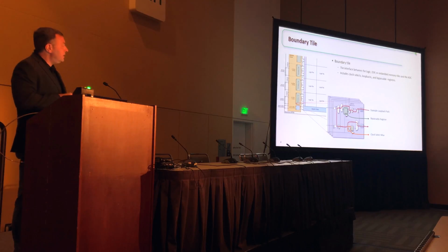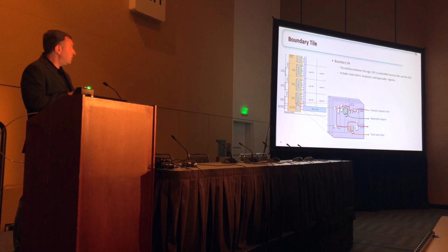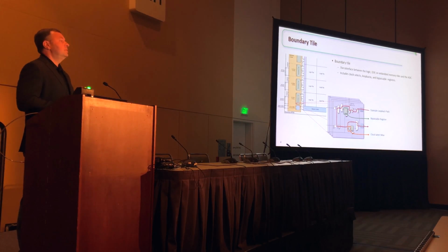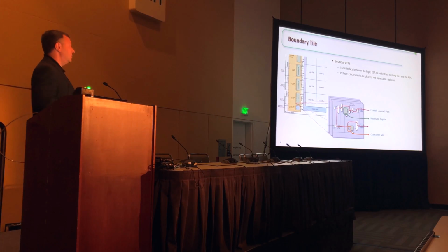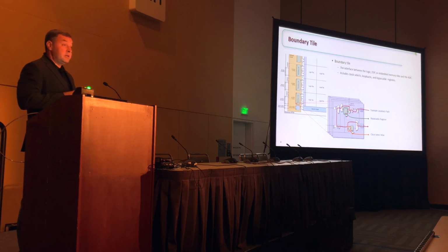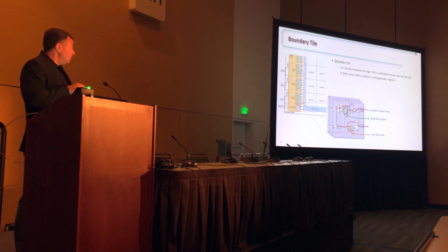Inside the boundary tile, for each input and output, in our SpeedCore embedded FPGAs, we have a bunch of features built into hard logic. One of the first things you'll notice here is a loopback path. You can configure the FPGA so that the output from the FPGA cores loops back into the FPGA. This isn't particularly useful in traditional designs, but it's really useful when you're trying to do the ATE testing of your device, when it's coming off the manufacturing line. You've got all these loopbacks and you can test all of the different options. You'll note here we also have loopbacks in the opposite direction. We then have bypassable registers, which is one of the key things we'll talk about today, and we have a clock select mux, so you can decide which clock is being used for the input and output registers. Make sense so far?